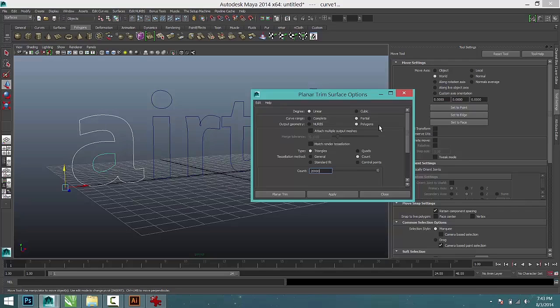One of the advantages of a polygon is that I can extrude, all right? So that if I start with a flat surface, I can then push it out and create a real 3D surface. So I'm going to stick to the option that I have here, polygons, and then come down here and I'm selecting the type of tessellation or division that I want.